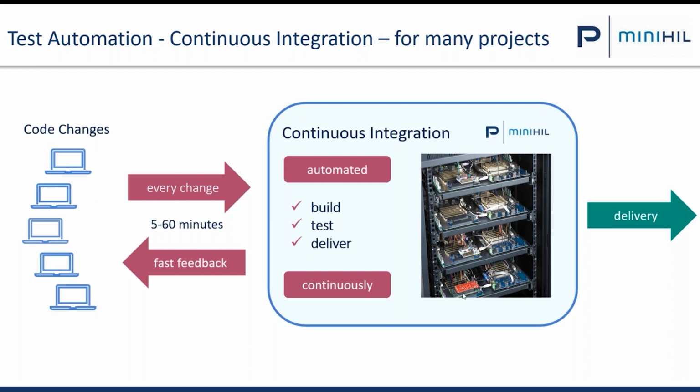And here you see a setup for 8 miniHIL projects. So 8 different projects, here with an Oryx board, here with an STM32, and so on. So 8 different projects in a rack attached to the server. The server can use this hardware to really run its hardware in the loop tests, its hardware software integration tests.